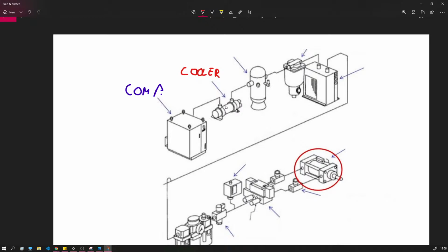But yeah, basically the first element after the compressor, which can also be incorporated into the compressor, is the cooler. We need to cool the air down after compressing it. And usually with the cooling, also some condensation may happen, and some of the water must be removed from the system. The element that also has a function as a cooler is the reservoir. But cooling the air is not the first and the most important part of this element, the reservoir.